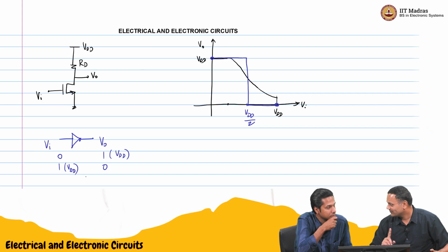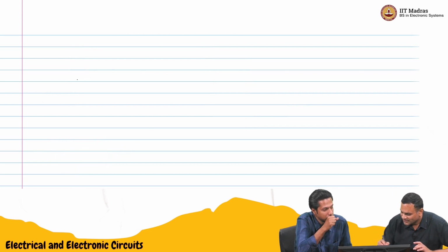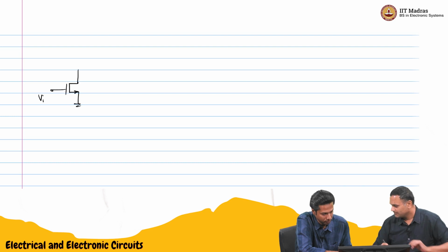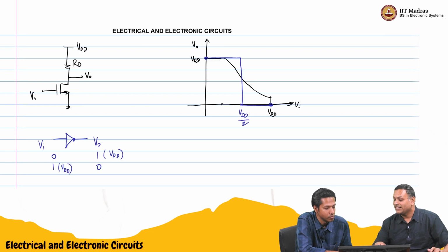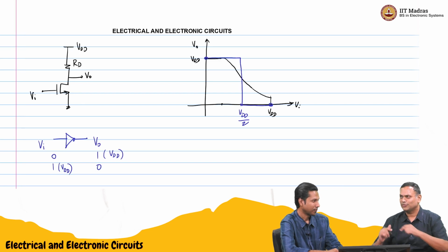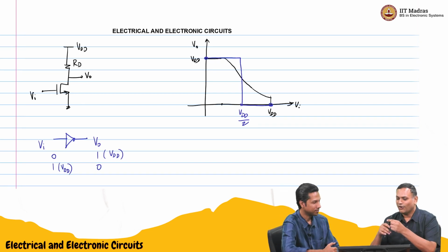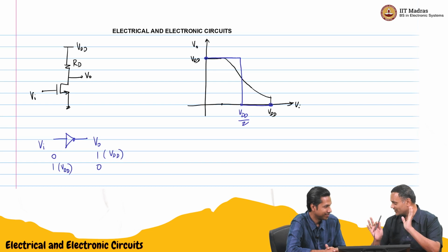And like you said, symmetry. So we will retain this part, VI, get rid of the resistor, but you still need some current to flow. There should be something on top, not a resistor. All the circuits that we have seen, we use transistors or resistors, and capacitors, but a capacitor is not going to be very useful here. You want DC current to flow. The only thing that you can do is use another transistor.